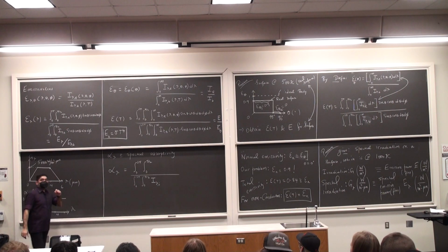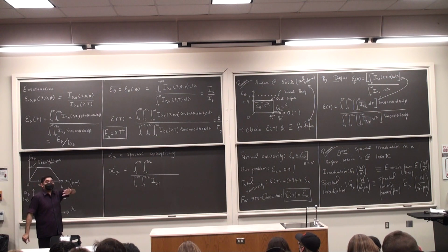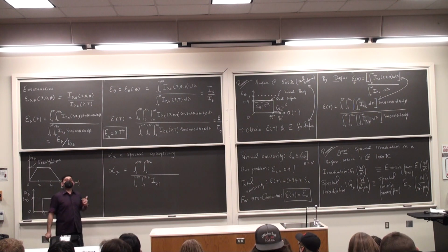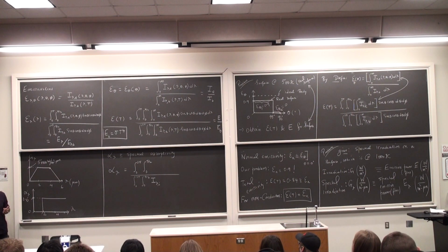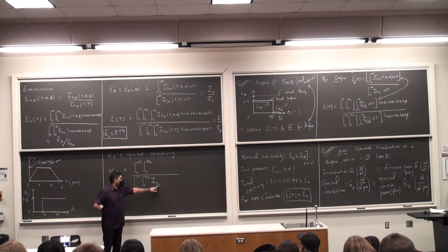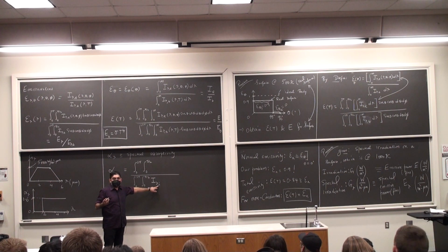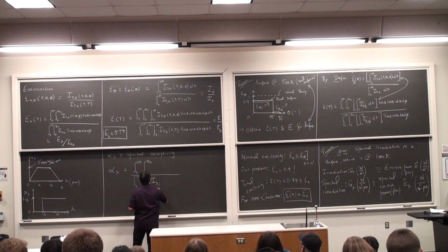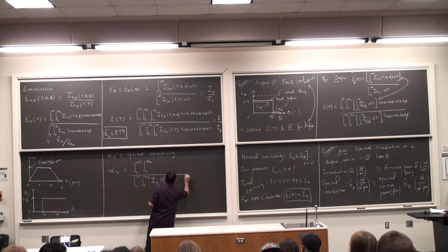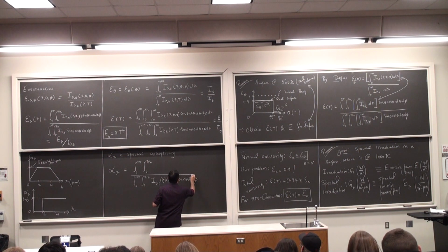Please notice that little I means this is the intensity of the incident radiation. This has nothing to do with a perfect body or an ideal body. There is no subscript little b there. That will happen once we study Kirchhoff's laws later on, okay, in the next lecture. At this point in time, this is just the intensity of the radiant energy that is coming from surrounding sources, which need not be ideal bodies. Okay? And this is going to be lambda theta phi sine theta cos theta d theta d phi.